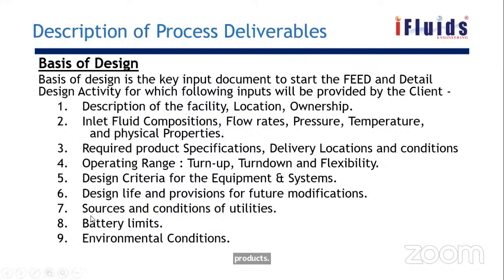achieved. And then the fifth one, the design criteria for the equipment and system. So those who are doing a separator, those who are doing the line sizes, they will be provided with certain data from the standards. So we don't need to go on our own. We need to follow the criteria given in the design. So whatever calculation we do, the input will be provided, in the sense of what standard we need to follow, what range we need to take, certain constant values. All those things will be provided in the design criteria.